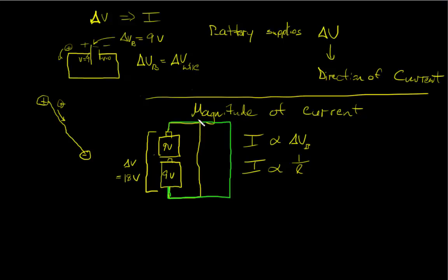Okay, so we could take it long, but what if I made it into a really, really fat wire? Then what's going to happen? Well, it gets easier to push the charges through. So there's some quantity of the wire that's determining this. It's determined by the length, the cross-sectional area, and the material itself. Altogether, that's just called the resistance. So instead of length, let's just change this: the current is inversely proportional to the resistance of the wire.